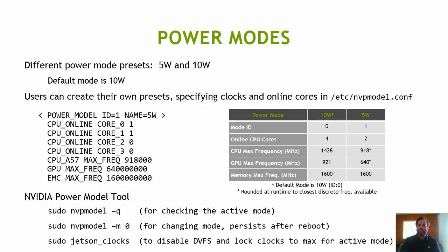NVPModel and jetson_clocks are command line tools, but in the next JetPack release, you'll see a little NVIDIA icon appear in the status bar, and this will let you configure and monitor the power settings of the system through the GUI.